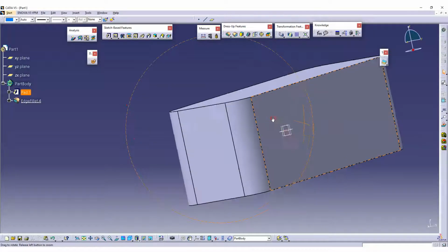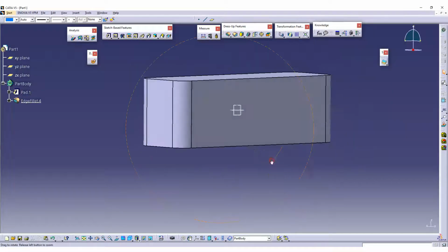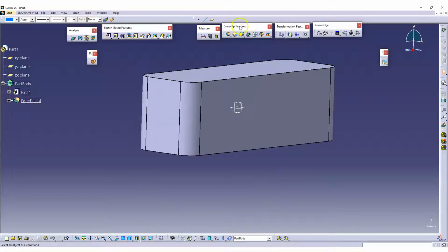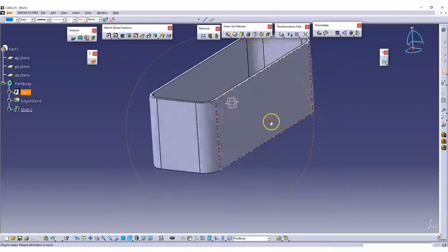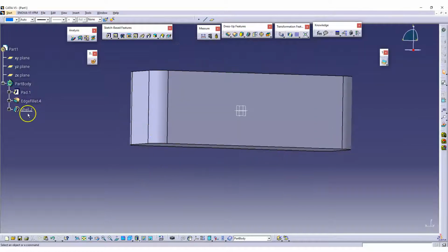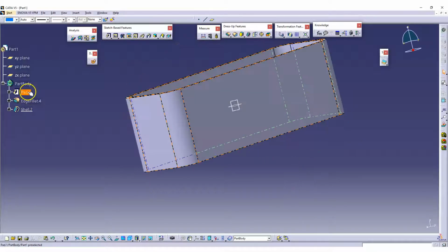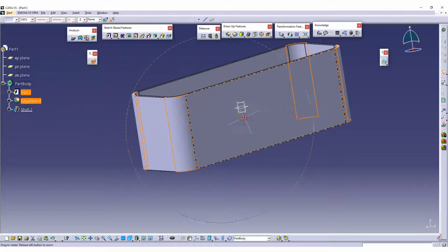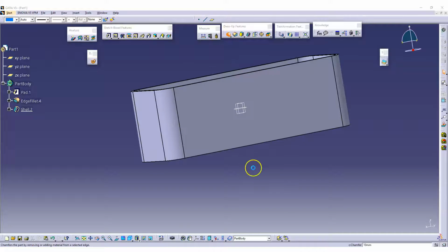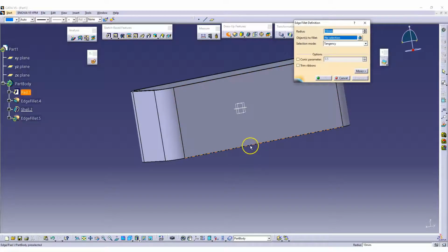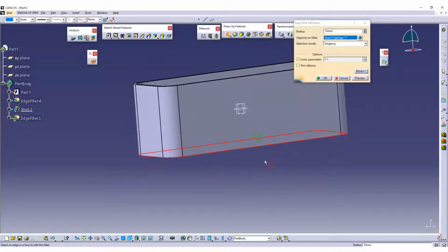You got this one. Then now I'm just telling you, give a shell. By mistake you have done this shell for a thickness of 5 mm, for example. You got this one. Then what you do after giving shell, observe carefully, I just created pad, then I created edge fillet. After creating this one, I will create fillet in the bottom. This could be the problem. Most of them do it. What's that? There is no difference. I created this. What is wrong that I can create next to this one? So I just give, for example, fillet of 5 mm.